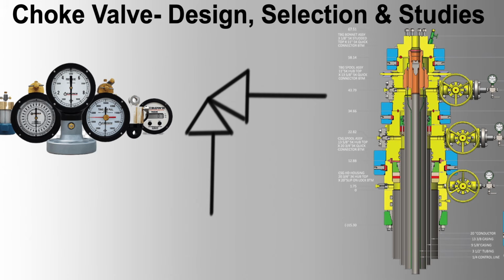2. Trim components. Tungsten carbide: high hardness and erosion resistance, suitable for high velocity and abrasive fluids. Ceramic: excellent erosion resistance, used in highly abrasive environments. Hardened stainless steel provides a balance between corrosion resistance and durability.